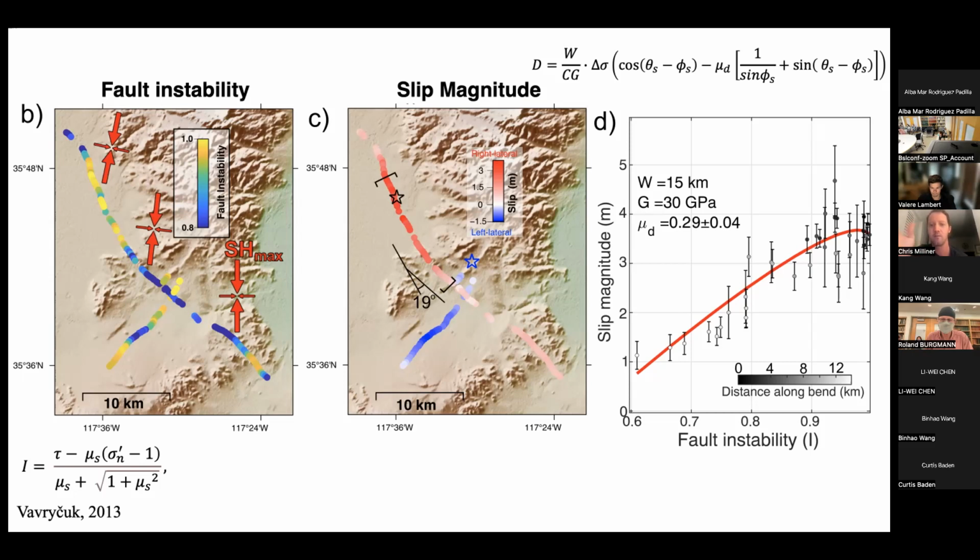If you're looking at individual fractures within the fault zone, then you're going to be subject to stress interaction between fractures within the fault zone, and you're not going to be sensitive to the regional stresses or the ambient stress field around the fault zone. So that's my only concern. But theoretically it should be possible if you can get the full total slip vector.